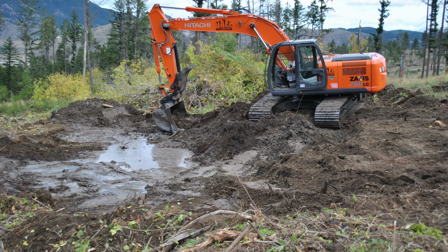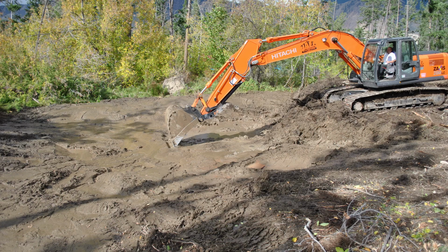Tim is digging the wetland to be deepest in the middle with gradual inside slopes. Water is filling the basin as he's digging. Here you can see why it's important to use a large excavator to build wetlands when using the groundwater technique. This excavator that weighs over 40,000 pounds can stay on dry and firm ground and then reach into the saturated soil to dig the wetland without getting stuck. It would not have been possible for a smaller excavator to build these wetlands.